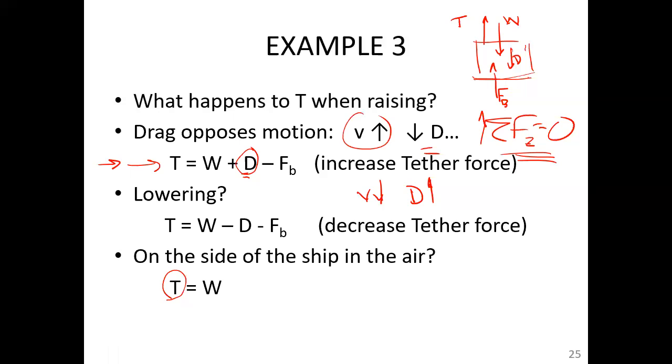And right now we're just talking force equilibrium. How many times have you seen in the news a crane that has collapsed? Typically, that's a moment equilibrium. And what people neglect to think about at that time is the force equilibrium may be okay, but the moment equilibrium may not. All you need to know, these same forces are acting, but you need to know about the point of rotation in which they act when you're trying to do a moment equilibrium. That would be the difference.